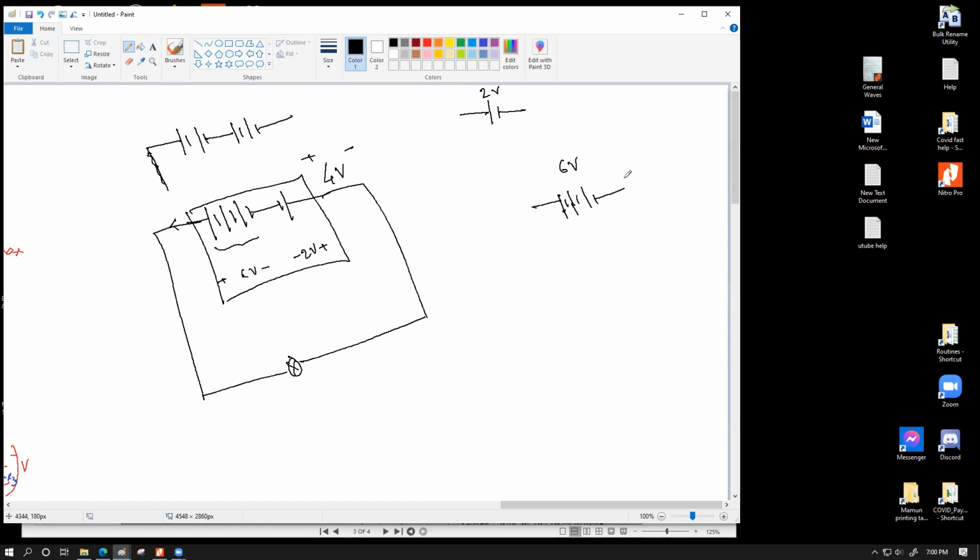The moment you connect the charger, the charger must produce a voltage across this battery. I mean, this circuit is actually working over here. The charger unit must produce a voltage opposite to its natural current flow. So let's say this one should be the positive end of the charger unit, this should be the negative end of the charger unit, and this must go in this way. And the delivered voltage should be somewhat bigger than 6 volts.